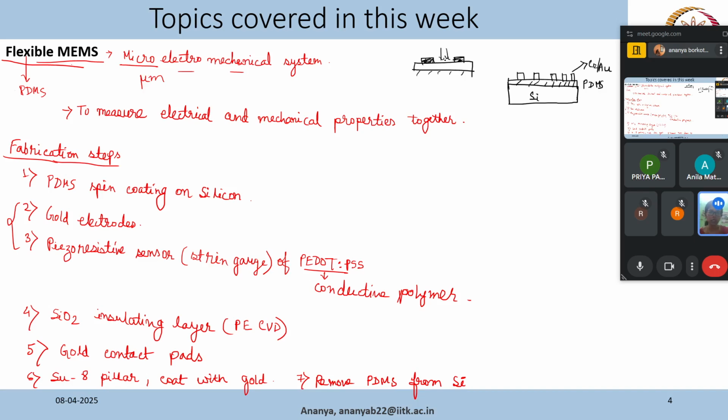We are considering directional etching, say some physical technique. And after that our structure will be something like this. Gold will be here, there will be photoresist, and then gold and photoresist, and then we can remove this photoresist using acetone very easily, and we will have these gold electrodes.